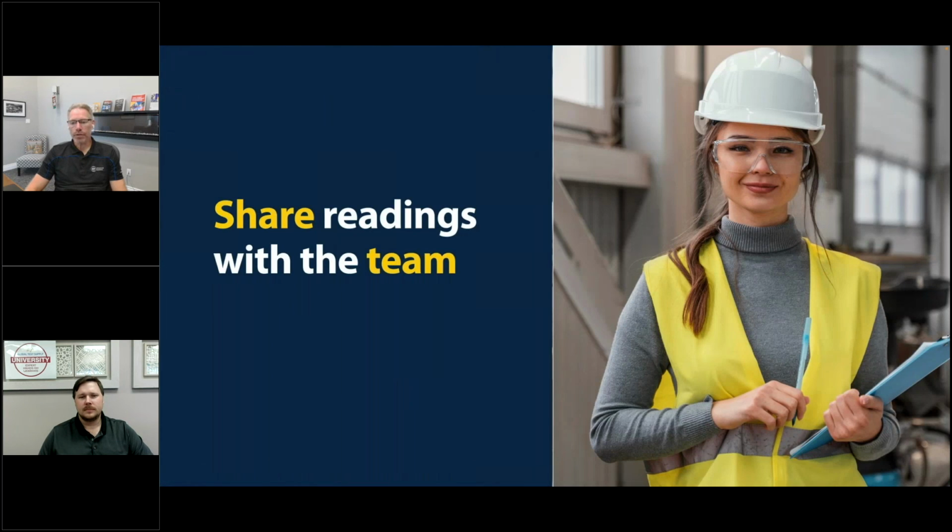And of course, if you don't document the task, it never happened. Your ultrasound assisted lubrication program has to log everything: grease consumption, success or failure of the task, condition of the asset, and much, much more.